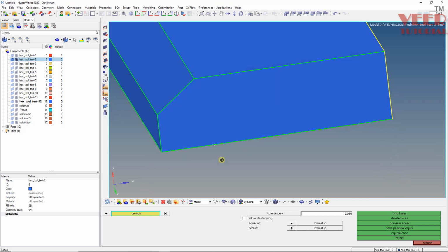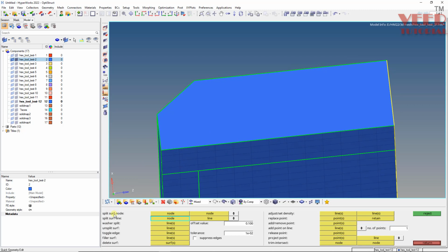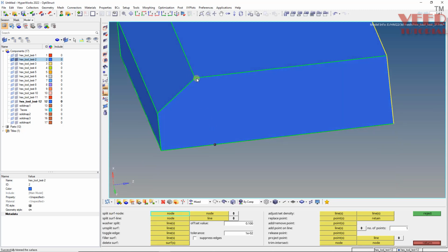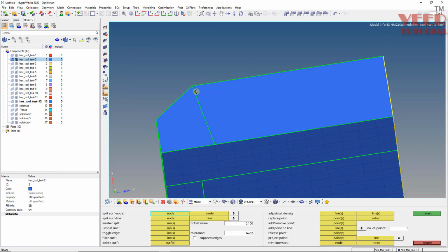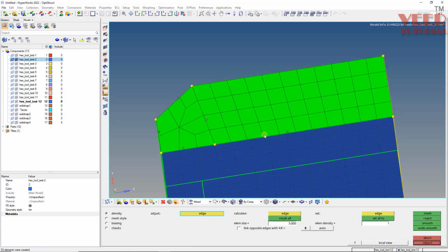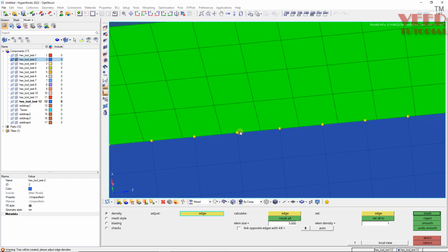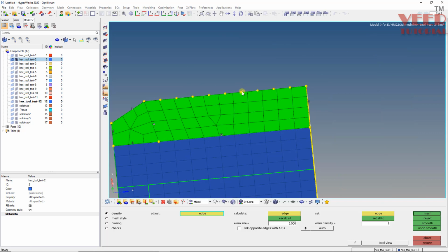Okay, so what I do, I will take some projection from this first one, from this node to this node. Okay, little bit inclined line, but it will work. So F12, select this face and this face. So here you can see mesh is not connected. Let's change the number by 10. Okay, 10 is working here like this.